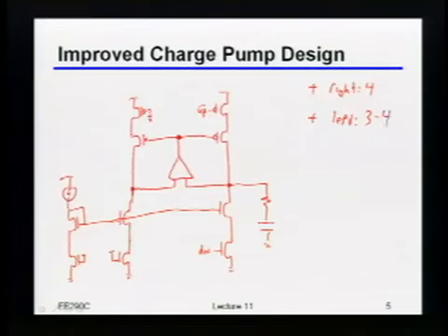So in general, how do you decide what's plus and what's minus? Negative feedback should be stronger. Yeah, the negative feedback is the loop that you want to quote-unquote win, right? Okay, so how are you going to know which loop is going to win here? You break both the ends of the op amp and put a delta V source and see what comes back.